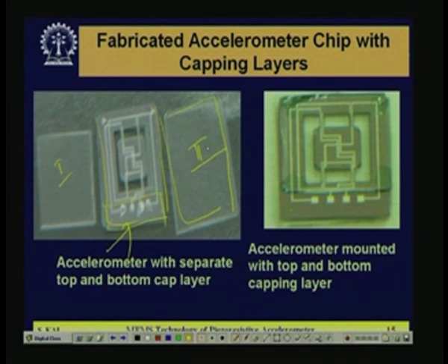So if you put the bottom layer at the bottom and the top layer at the top, then it looks like that. You can see here, this is the glass layer 1, and at the bottom is layer 2, and in between them you can see the bonding pad regions are open, so that you can take bonding here, here, here, and here. So 4 bonding pads are required, 2 for input, meaning the power supply, and 2 for output, which are outside the glass cover. With that, substrate to glass bonding is over.